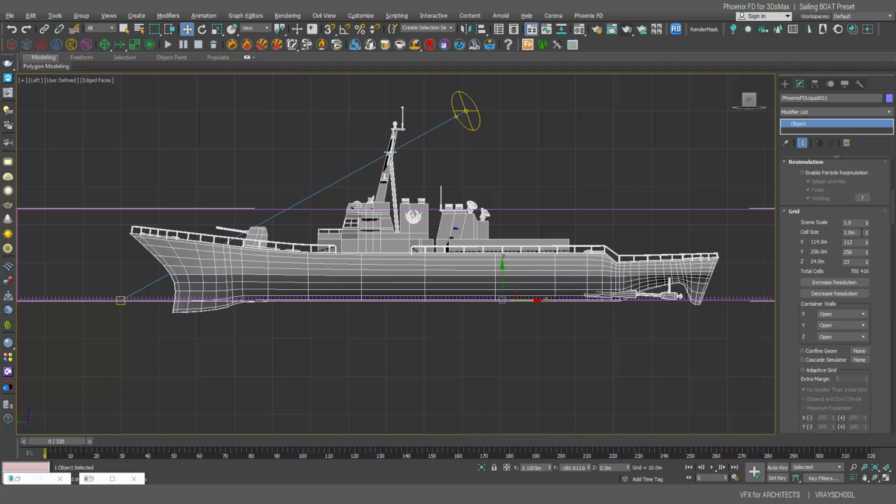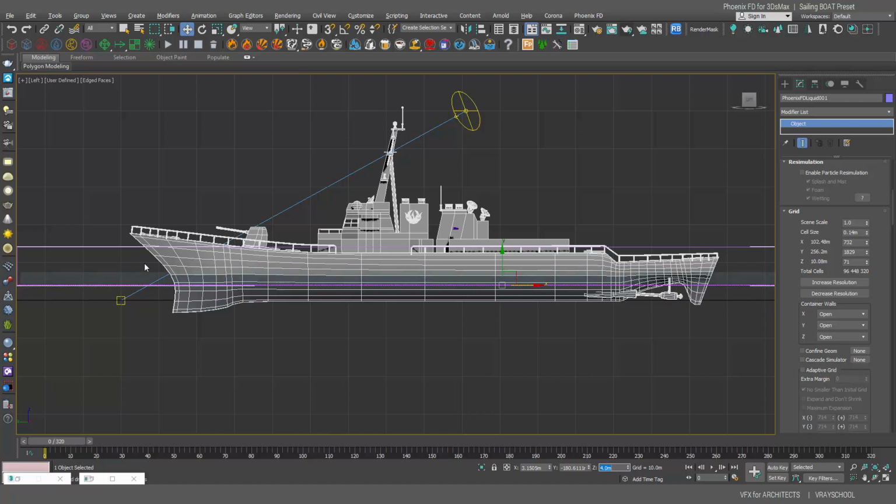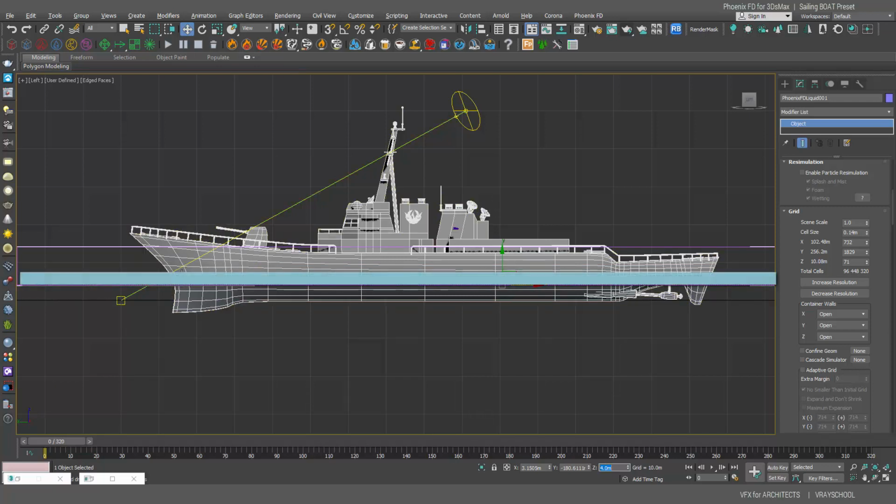I actually need to use a smaller cell size. Those, as you can see here, are separations. This is the cell size, so I'm gonna use something much smaller, 0.14, and much smaller here. All right, now this one can go slightly up somewhere here, so that's a perfect breaking point for the wave.